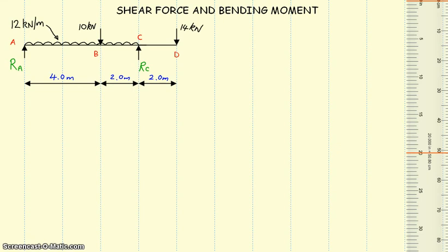So pushing on from there, the first fundamental question that we always ask ourselves is: is the beam symmetrically loaded? And obviously we can see straight away that no, the beam is not symmetrically loaded, and therefore we will not be able to use the sum of the verticals equals 0 to calculate our reactions, and we will actually have to use moments, because there are no horizontal forces on the beam either, and therefore we cannot use the sum of the horizontals equals 0 to calculate those reactions either.